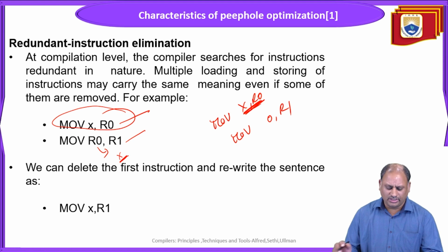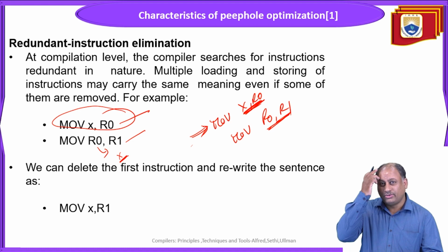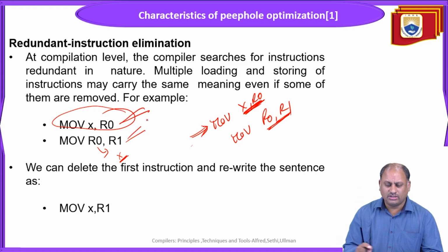But instead of taking a separate register and storing the contents into it, we are not going to take this. Simply we write the registers r0 and r1, so that the commonality, the loading of things several times, is avoided. Here r0 is loaded once in the first instruction, and then loaded again in the second. So multiple loading and storing is to be removed in this case.